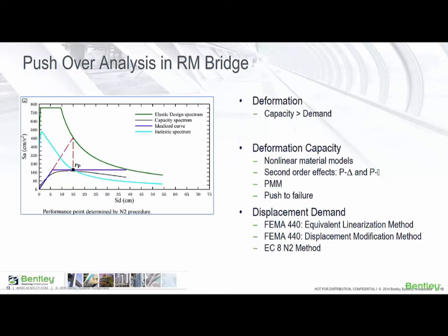These are nonlinear static procedures which convert multi-degree of freedom models to equivalent single degree of freedom models and use response spectra as opposed to ground motion records to estimate global displacement demand.